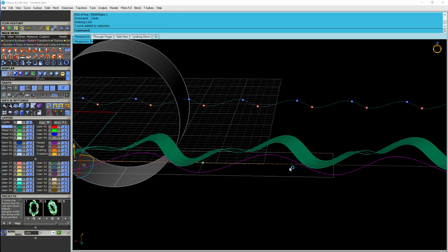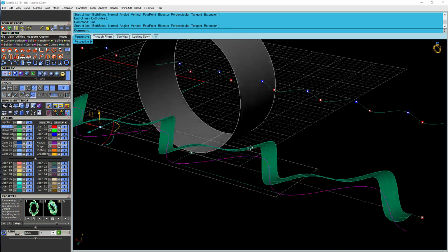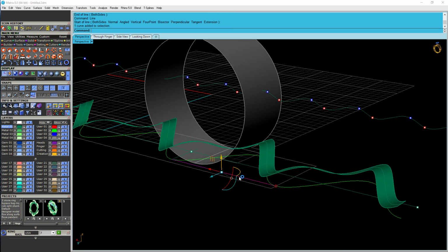You can either just come in this view and snap to that bottom curve, or you can turn on this project here, and that always puts any points that you try and put out on a curve when you snap something onto the construction plane, so it projects it at all times. But should be good.